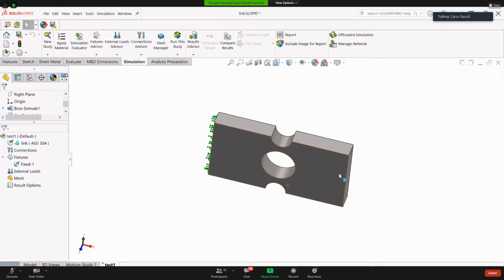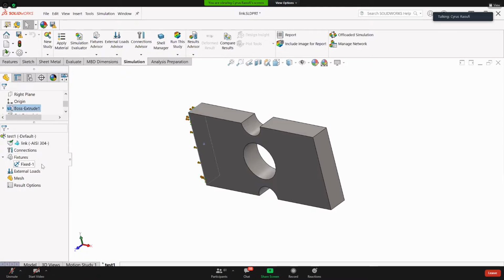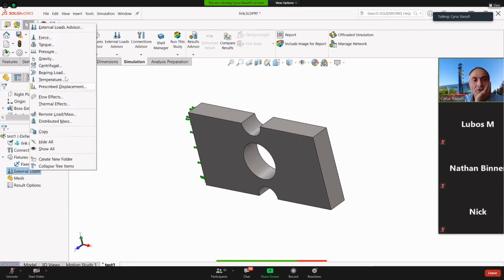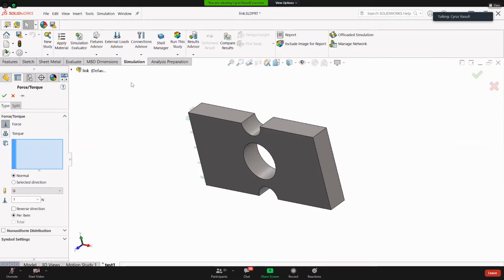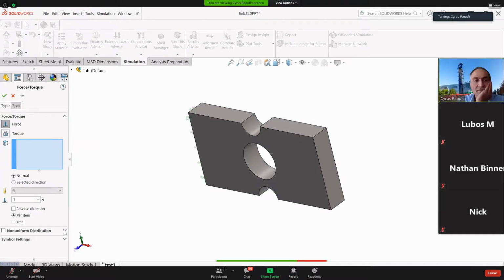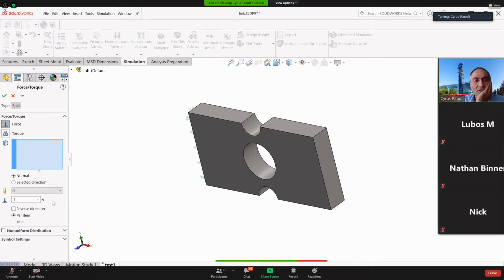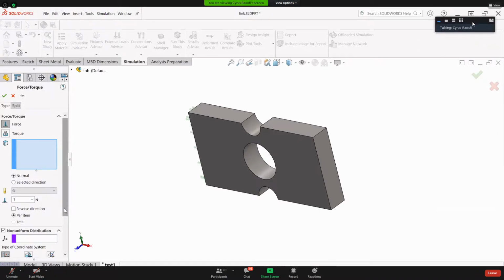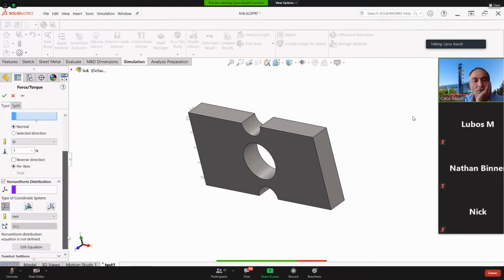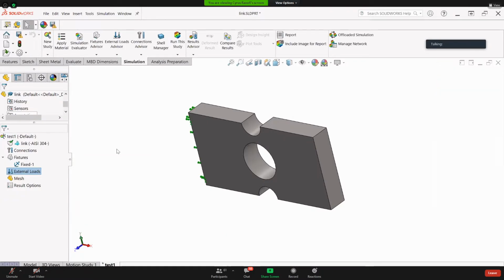All right. Now, the next step is we said we are going to apply forces. I'm going to apply force. And here again, in terms of force, we have different types of forces. As you see here, we have distributed force, we have uniformly distributed force, and we are going to practice some of those forces in chapter 4. For now, you know that we can apply non-uniform force, we can apply uniform force, and apply it to the faces that you want, or to the edges that you want later on when you go to shell. Then you can apply force.